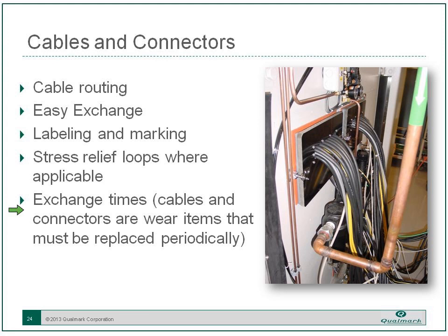And keep in mind, as all of us in test know, that connectors are wear items, and particularly with the vibration that we're doing here, you need to keep an eye on those to determine replacement schedules so that you're not damaging pins on new products because of scratches in the sockets on your cables that you've been using in HASS.